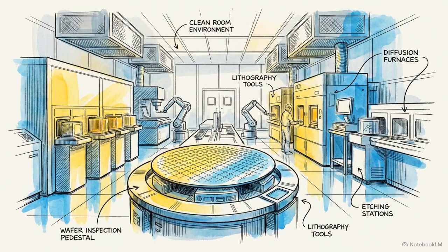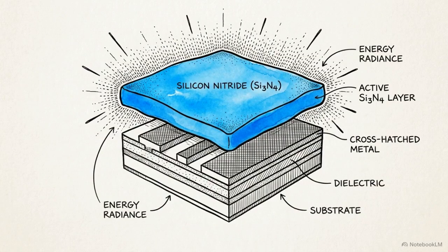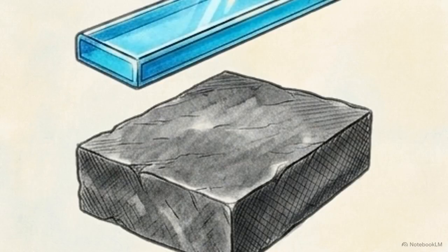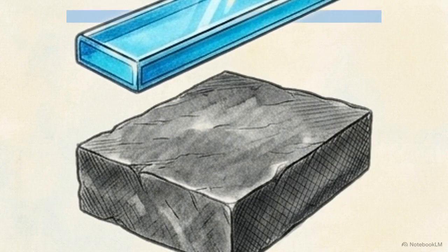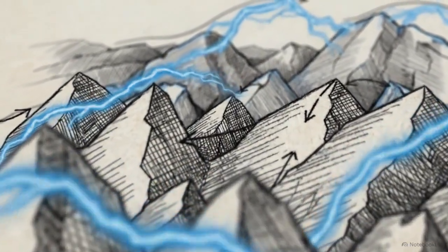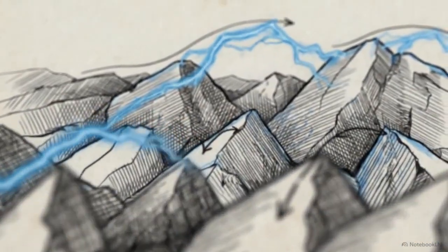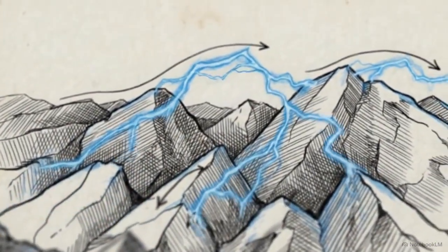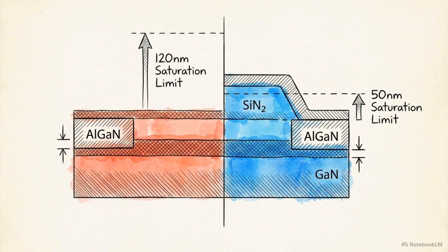Zooming out, these mechanisms present strict rules for the physical engineering of high electron mobility transistors. The first principle is that passivation is a highly active variable. It directly modulates the 2DEG by serving simultaneously as a trap neutralizer and a strain generator. The second principle is that tunneling leakage is inextricably linked to this precise balance of surface charges, rather than to ambient temperature. Finally, adding architectural spacer elements like a gallium nitride cap physically restricts the threshold for carrier saturation.